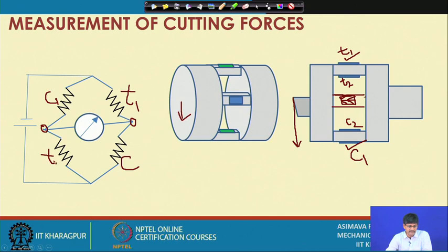So, if we put these in this manner, the advantage is that we are going to have a distinct drop here, which is different from this one, because this will be low resistance and this will be high resistance. So, voltage will be dropping considerably at this point. This will be high resistance, this will be low resistance. So, voltage will not fall so much. Okay. So, this way we will register a change here at this particular point and we can read off the value